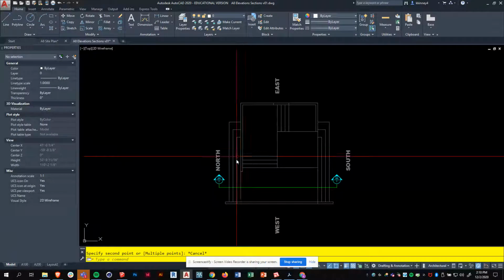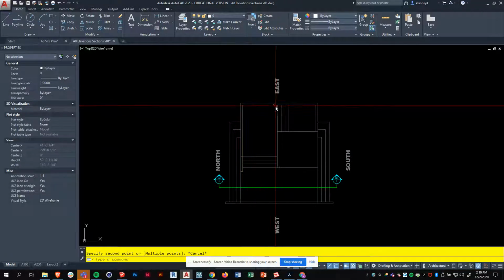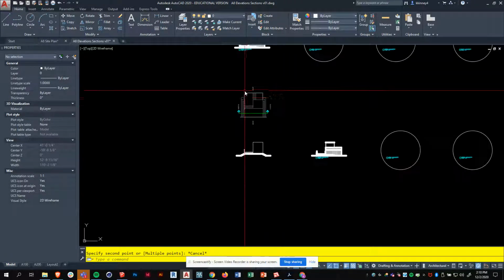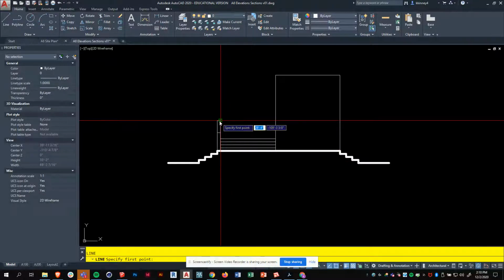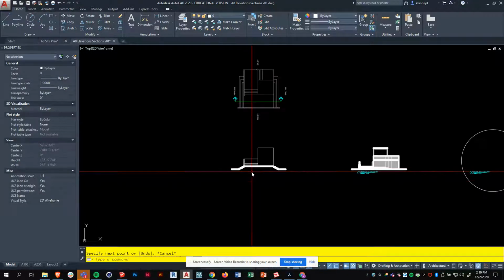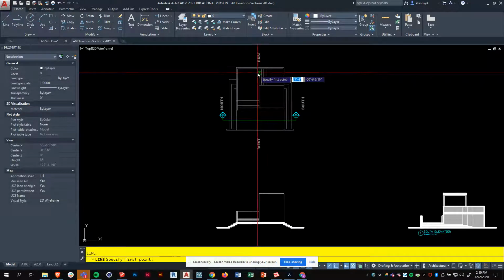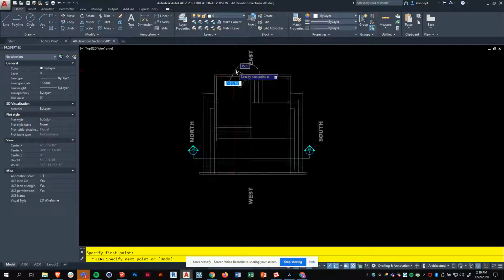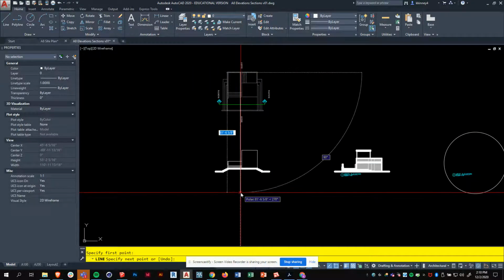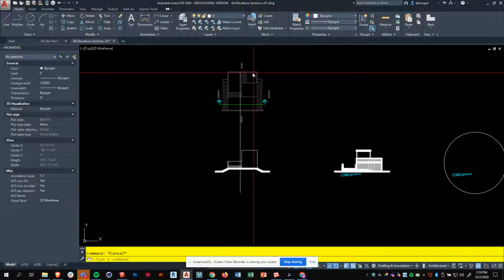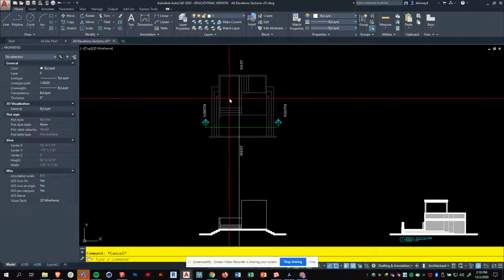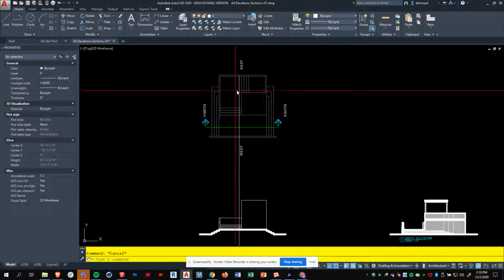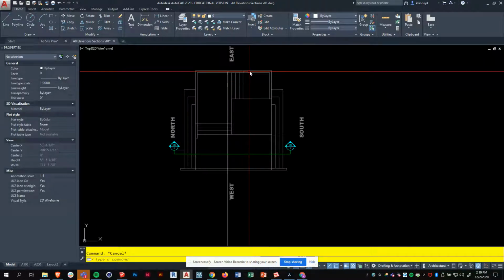Okay, now that railing goes across the back and then it starts angling up at this point. But let's just get the line in that goes across the back. But now I have to draw a vertical line where it starts angling up to the top level. Now this is going to be a little tricky. So if I bring this down, okay, I know that this is 2 feet off the ground, 4 feet off the ground, 6 feet off the ground. Top of the railing is 9 feet off the ground because 6 plus 3 feet is 9 feet.